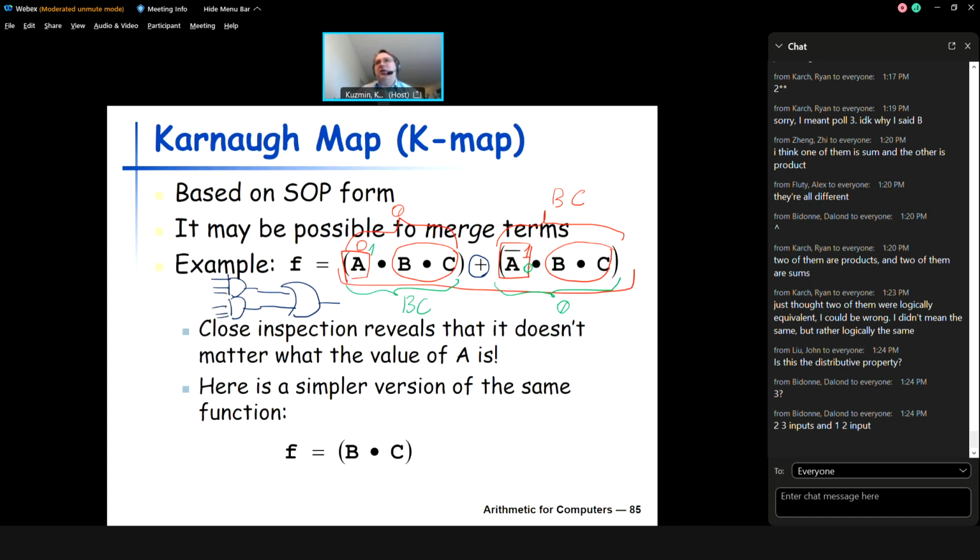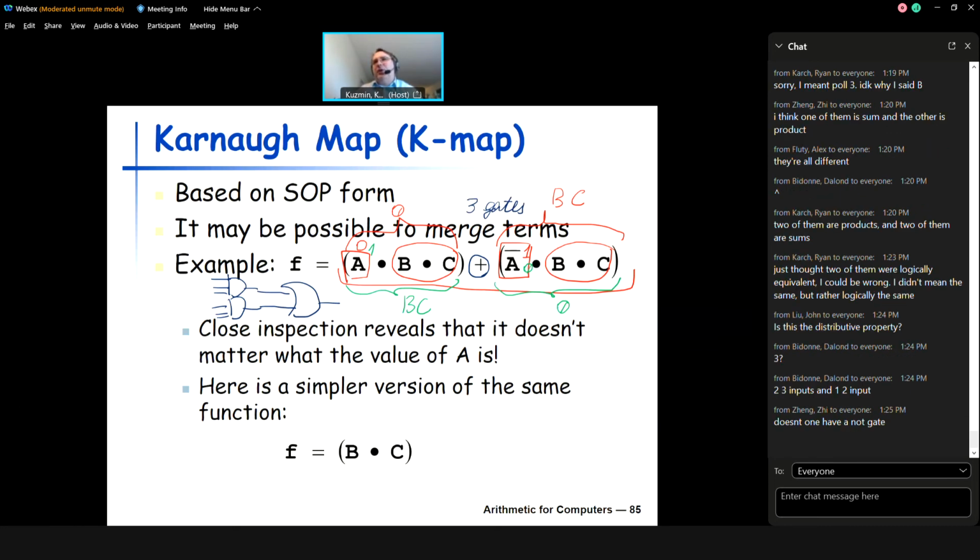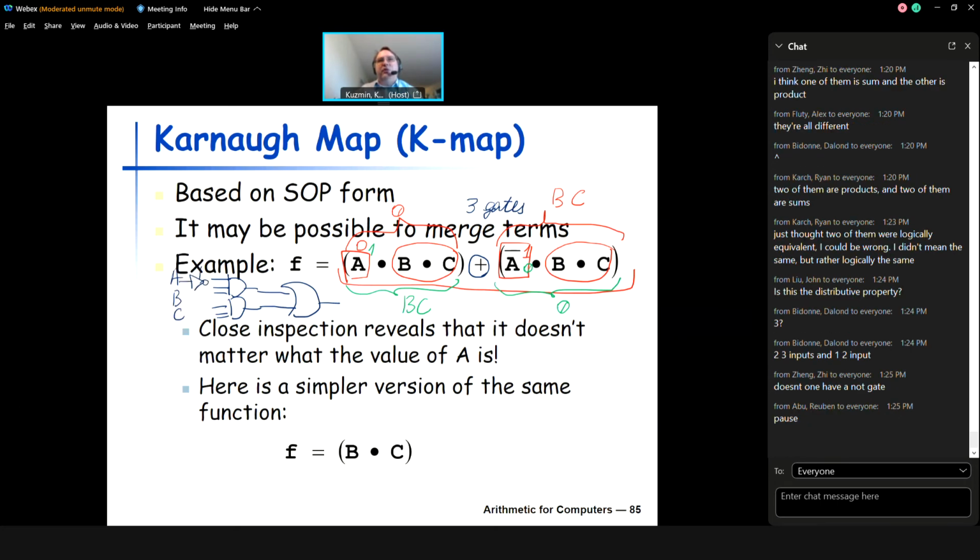Okay, so exactly 3 gates. You probably need to practice this a little bit so that you can see the number of gates directly from the formula without having to draw the circuit. It's okay to draw the circuit; it just takes a little time, but with more practice you would be able to say, oh, this one is 3 gates. It's important to note that in this particular case we do not count NOT as a gate. If we say that you should count all gates, including NOT gates, and we know that we are only given A, B, and C, then you would need an additional gate to produce a NOT in this formula. So that would be 4 gates.